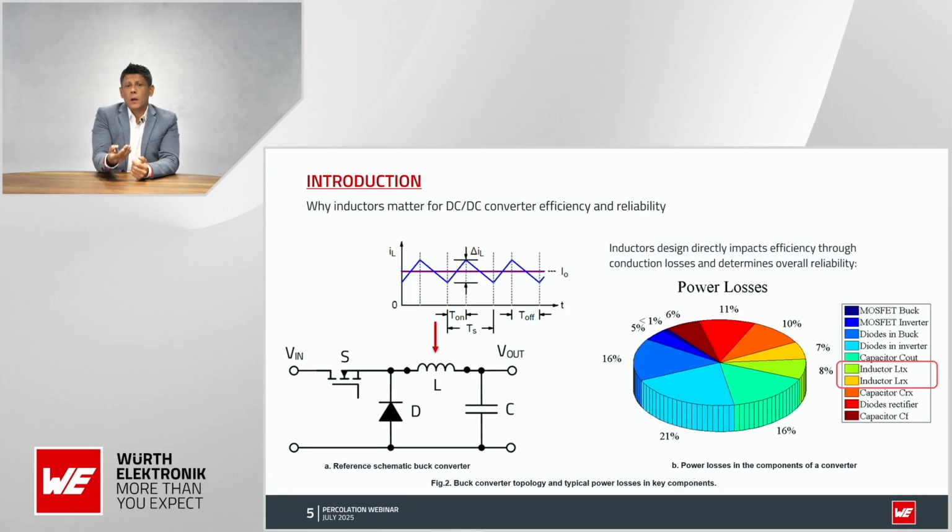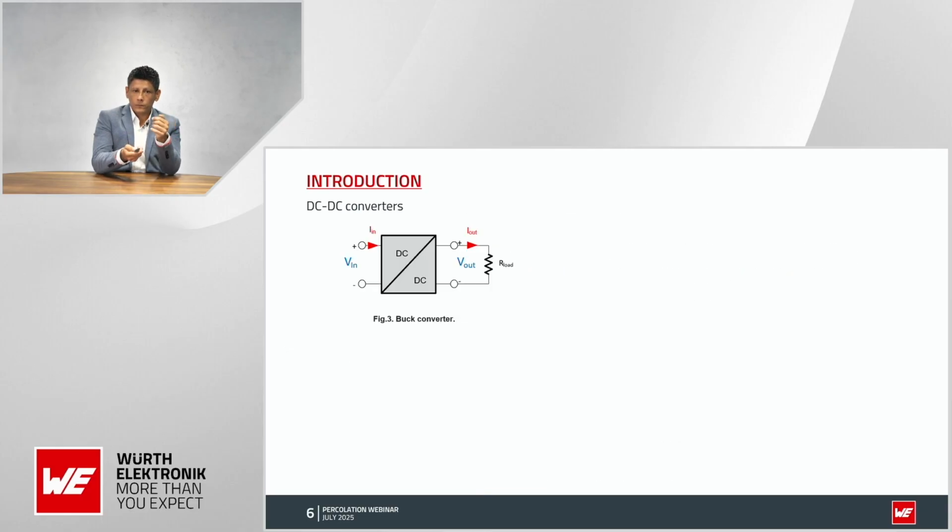But when we speak about reliability, we expect that the first one to fail is going to be the capacitors. Then let us speak about the cooling system. That is the one that's going to fail. There are a lot of things that can fail, but we never thought that one of the failure reasons could be the inductors. And there is concern based on molded power inductors because the technology is totally new for some of the customers.